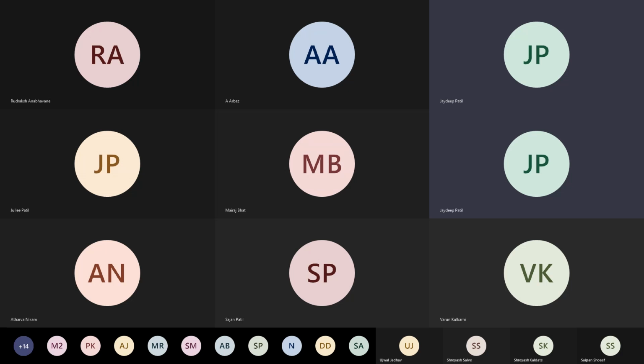It is the ratio of speed of driven shaft to the speed of driving shaft in terms of radian per second or RPM. Omega 2 upon omega 1, or n2 upon n1, is equal to cos alpha upon 1 minus cos square theta sin square alpha. Now, what is this alpha? Anyone? Anyone tell me what is this alpha?